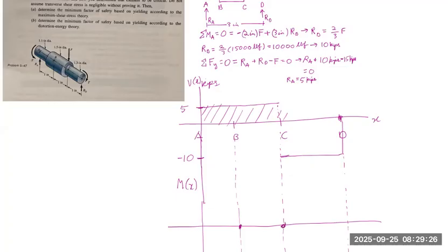And these points are critical because, as we said earlier, there are points at which there is a discontinuity, such as at B and C, but not really at D. But B and C are the critical points we have to calculate the bending moment for. So first we can just draw a general slope since we know that it will be sloping up until C because this whole area is positive and increasing linearly. So we have a linear slope.